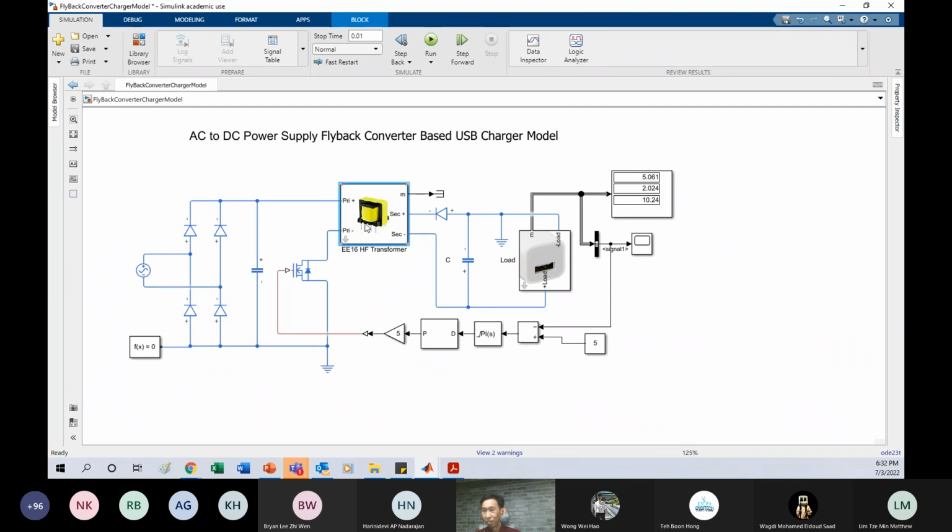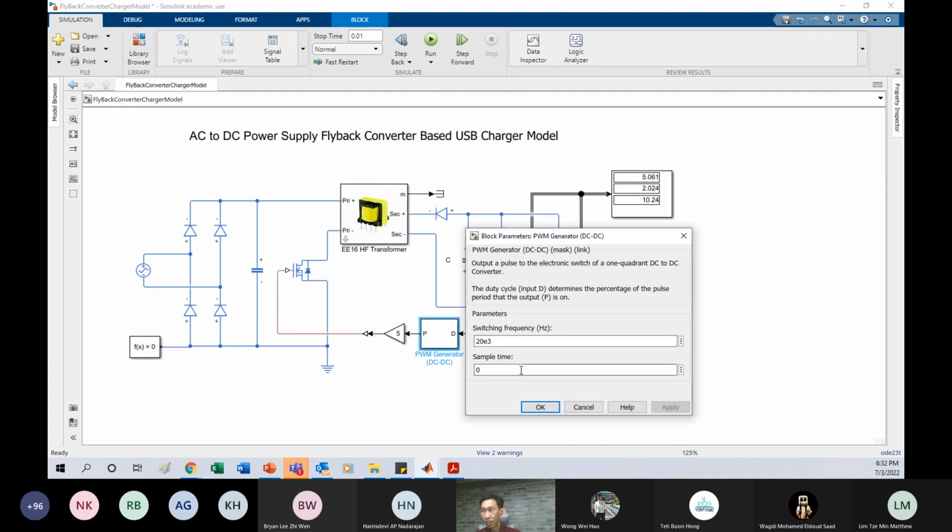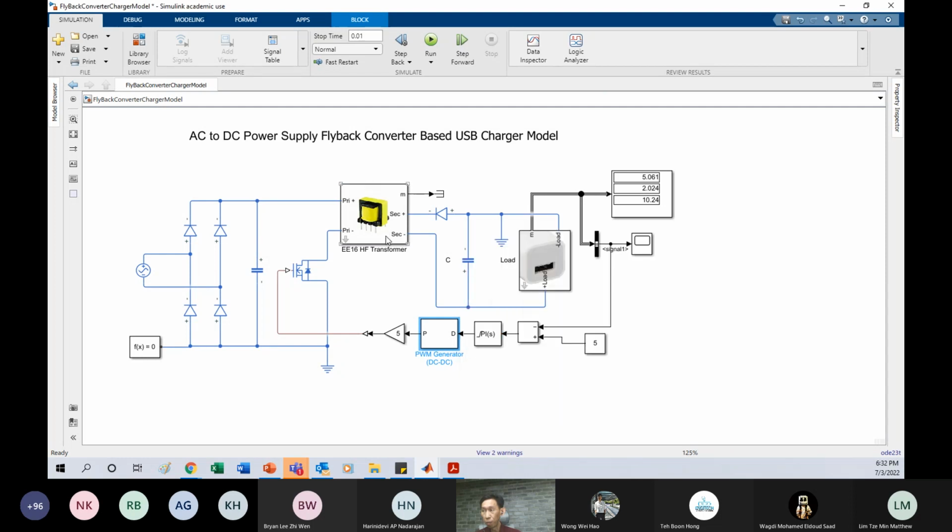But still, you can see the transformer size remains almost the same. It doesn't really grow big because of the power, because they use high frequency. Remember, now we're only using 20 kilohertz. If I want high power, this thing may grow big. I want to make it small, so I increase the frequency. And because it's only 10 watt or 100 watt, the losses don't really matter. And of course, you need to wisely choose the transistor and this diode, to make sure you have higher efficiency.